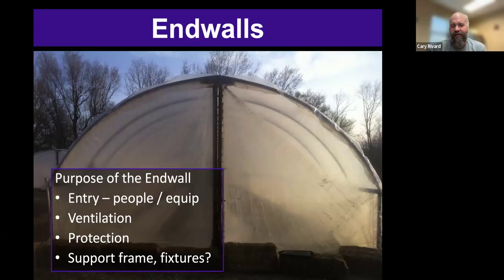I haven't really seen one like this for a long time because I think people are getting smarter and now using permanent and rigid in walls. This poly, it does not take much of a windstorm for it to cause a big problem. And unfortunately, especially if it's attached to these two by fours, it can start pulling the frame out of shape. And so you really want to be careful about that.